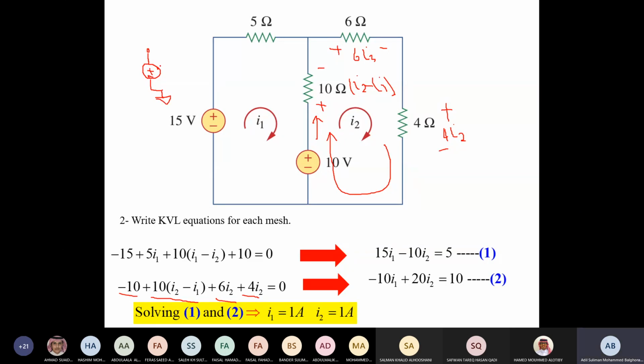We couldn't express the current when we wrote KCL over here, okay? And we said by inspection, if this is 10 volt, this is equal to 10. We had this situation. And we have another situation, a voltage source between two non-reference nodes like this. Same thing, and we said we enclose it as a supernode.